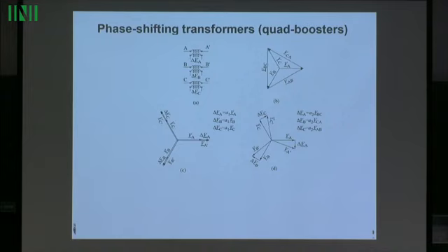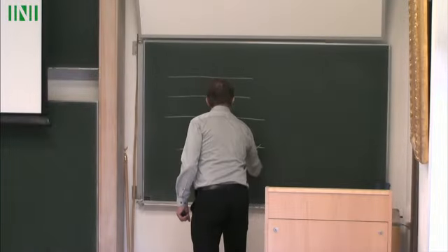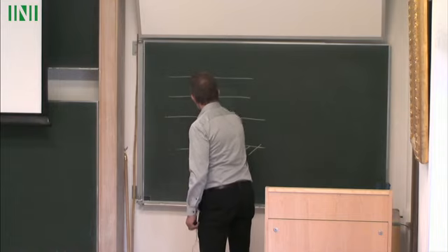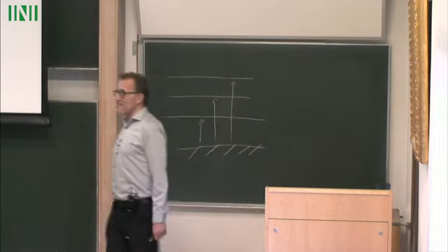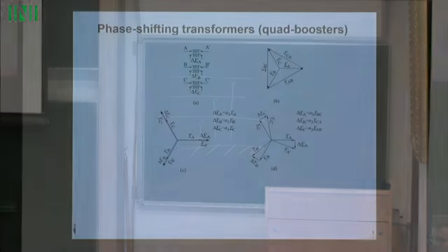So here look at those voltages. In three-phase circuits, these are phase voltages. It means the voltage on each phase of the three-phase circuit, 120 degrees shifted with respect to each other. So when you have three phases of the transmission line, and here you have the ground, those will be the voltages between a phase and the ground, the neutral, right?